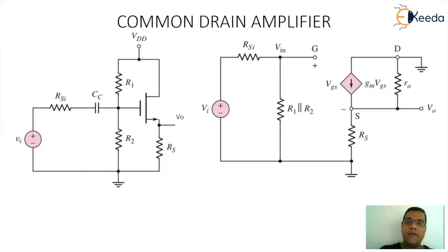And the input voltage for the amplifier circuitry will be VGS plus the drop across RS. So eventually, when you get the value of AV, which is VO by Vi, we will land up at the equation GMRS upon 1 plus GMRS, neglecting the effect of RO. If it is present, the equation will definitely consider the impact as RS parallel small ro.